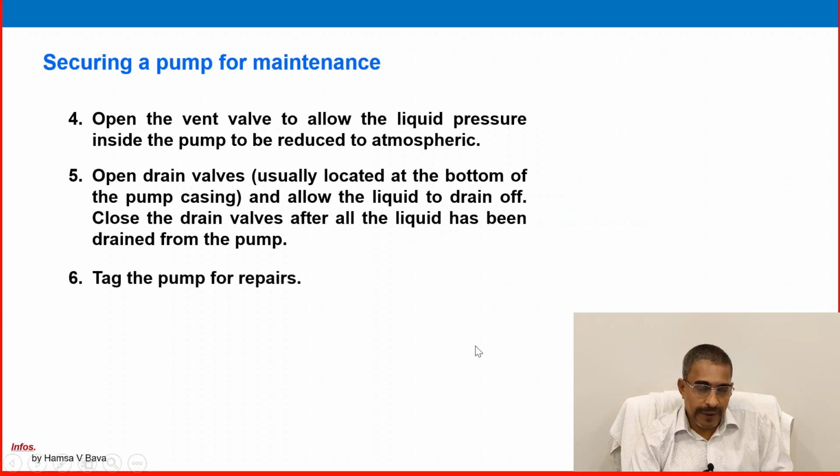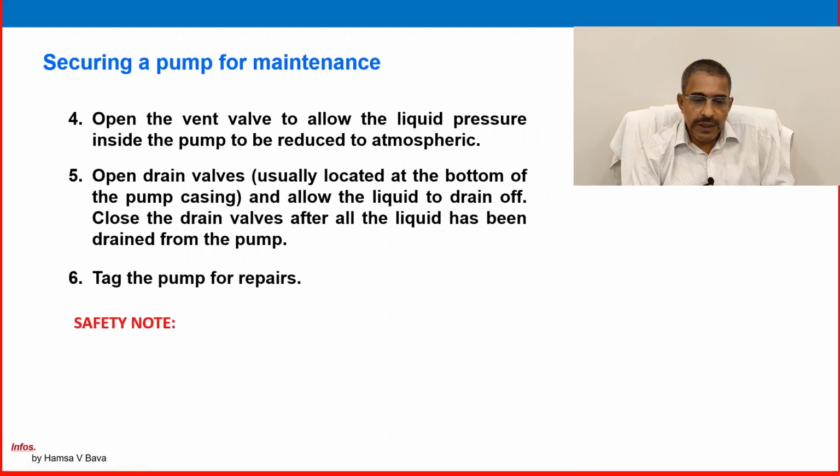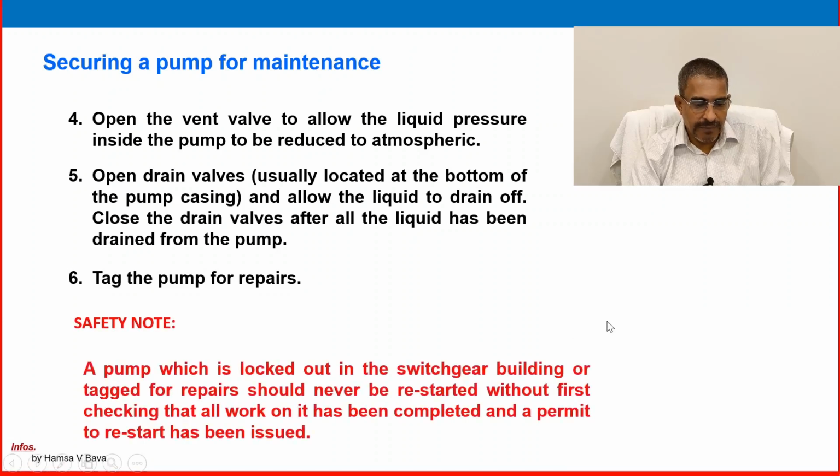Tag the pump for repair. So locking and tagging will be there. Safety note: a pump which is locked out at the switchgear building or tagged for repair should never be restarted without first checking that all work on it has been completed and a permit to restart has been issued. This is a very, very important safety procedure.